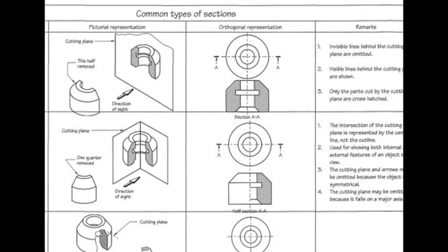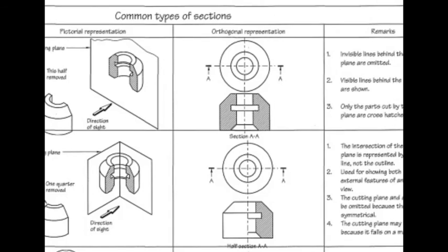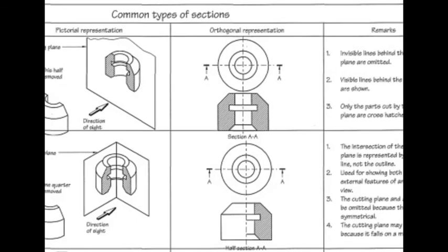And then in the correct position, you draw what you would see if you were to cut through the object on that plane. So the piece on your side has been omitted, and all that you see is what's in the distance. And now there's the matter of the sectioning lines, which you can see as the scratch marks left by the saw that did the imaginary cut.